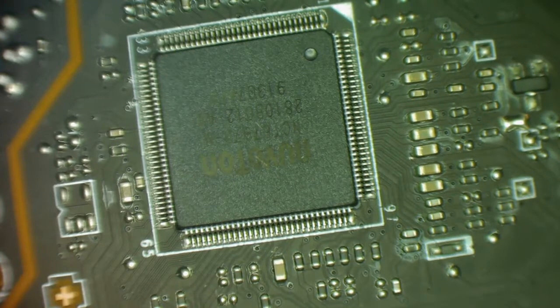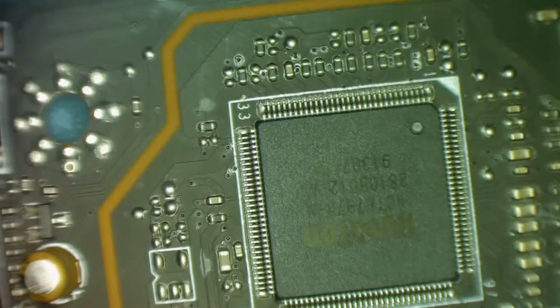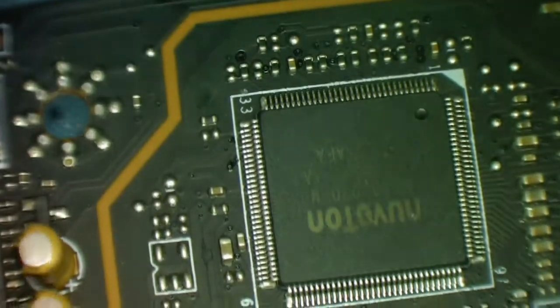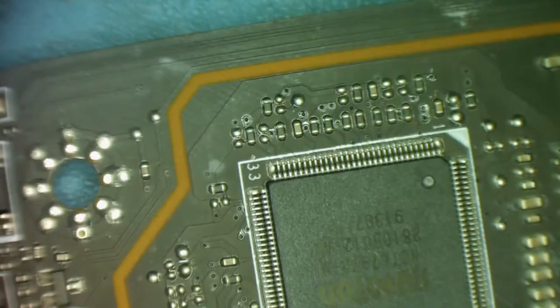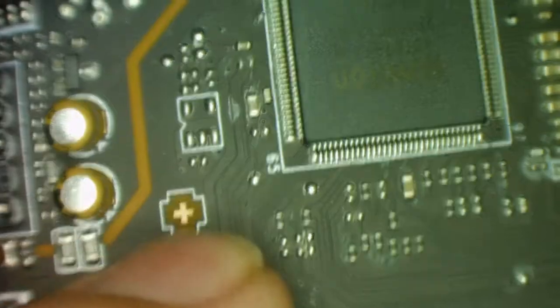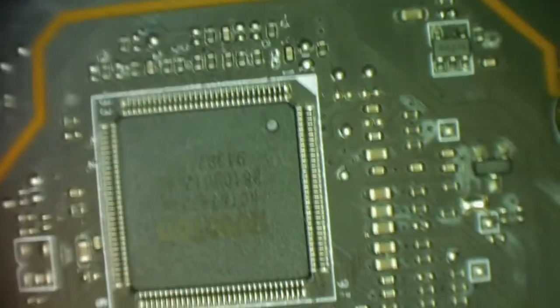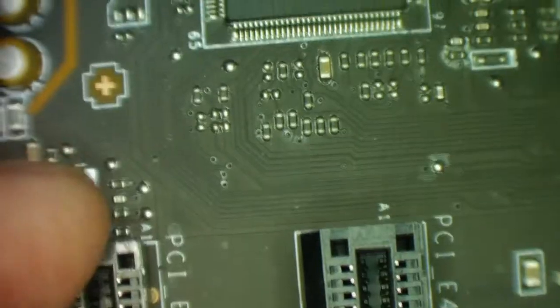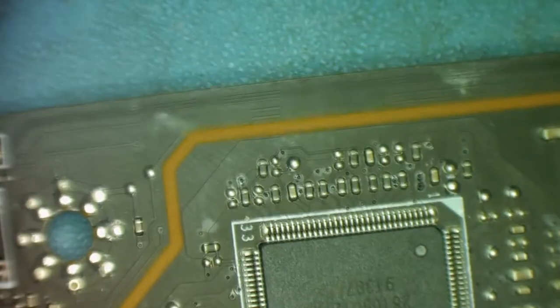This is what connects to the on-off switch, and this is what sends signals to the power supply to switch on. You may not send them directly. The north bridge will be involved, and possibly the south bridge. Sometimes the real-time clock's built into this, depending on the chipset, but I don't see any crystals around here, so I'm pretty much guessing that in this case it's not. I'd say the real-time clock is in the north bridge.